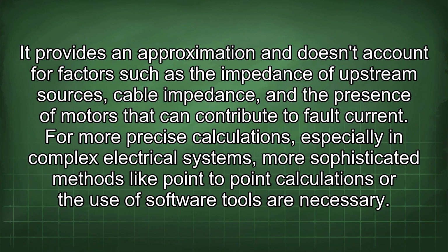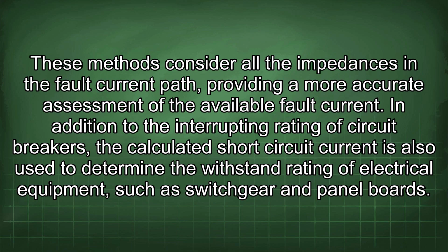For more precise calculations, especially in complex electrical systems, more sophisticated methods like point-to-point calculations or the use of software tools are necessary. These methods consider all the impedances in the fault current path, providing a more accurate assessment of the available fault current.